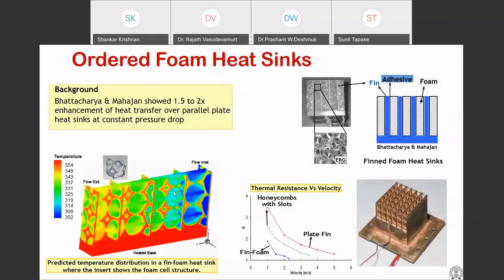So the sound absorption is also achieved. Sound, meaning noise here, within the same functional volume. She will talk about that in the next session. So that's another heat sink that we prototyped and tested. Manufacturing was very challenging. However, we were able to do it using 3D printing technology, not direct metal 3D printing, but we started with the plastic part and then did investment casting.